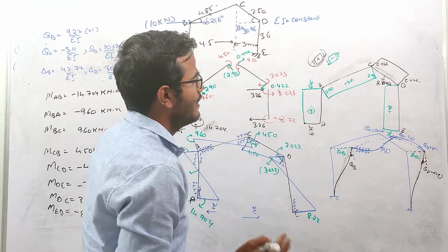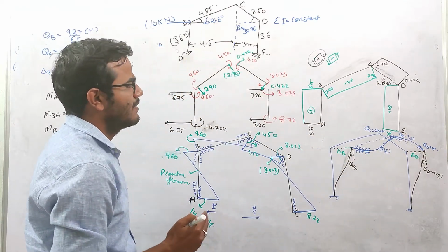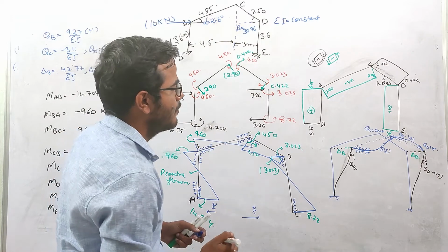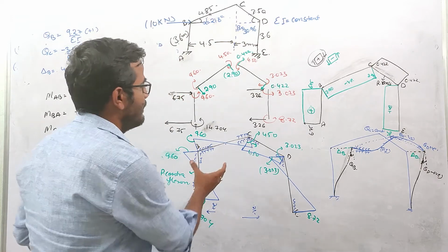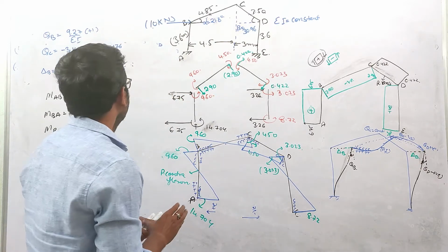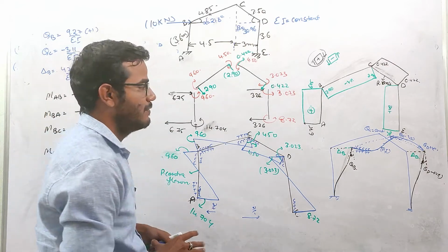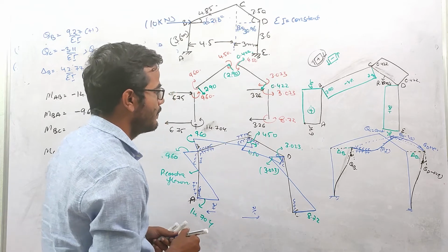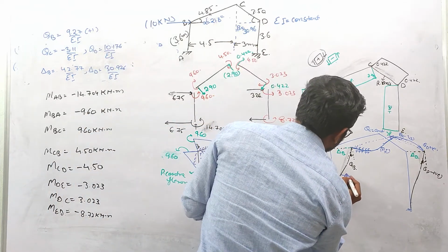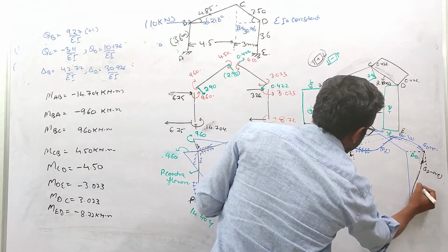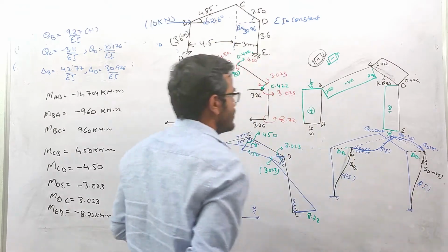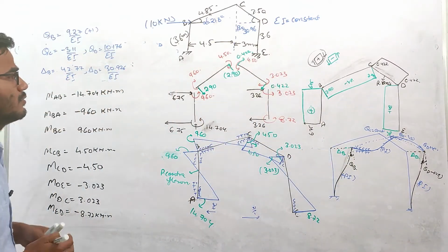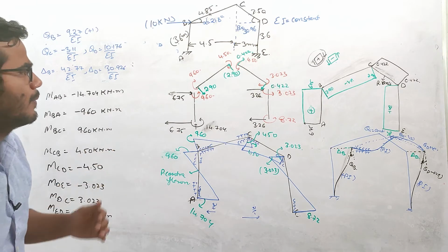Right? So this is basically the deflection diagram of this gable frame. Okay. As per the bending moment diagram which we have found, and also the displacement which we have calculated, whether the theta is clockwise or anti-clockwise, that thing is most important. Okay. And somewhere here we'll be having the point of inflection in the deflection diagram, where the curvature changes. Right. So we have discussed this problem in detail.